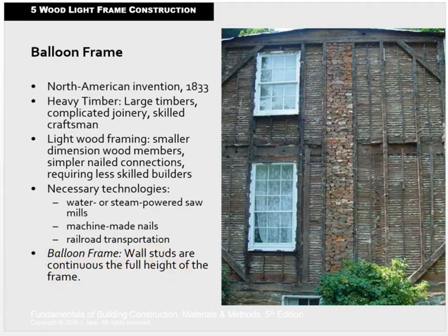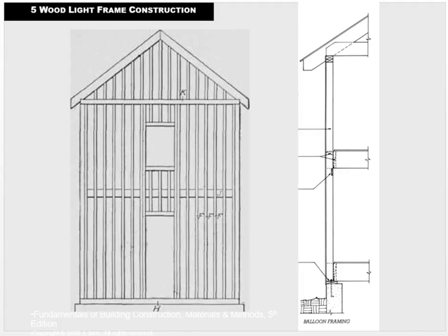All right, moving on. Here are two more images of the balloon frame. Here we see the studs extending past the second story, and here, in a wall section, we see the stud sitting right down on the sill plate. So there's our foundation, our sill plate. The joist is resting on the sill plate, and the stud is extending all the way up from the sill plate to where it meets the ceiling rafters.